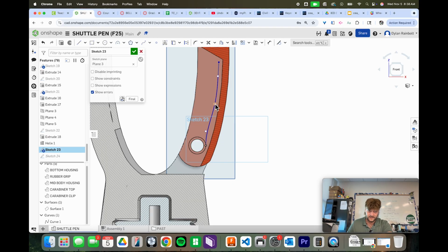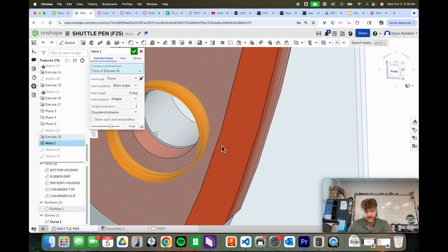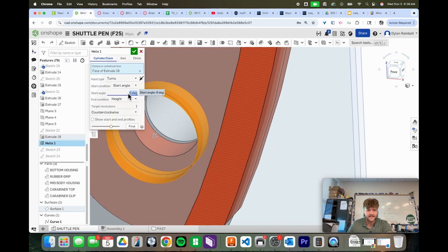It'll flank you. And so now, as you can see, we actually should probably rotate that helix just a little bit. So if I go in here, we want to move it clockwise. So let's try putting a 10 into here. Now that did end up moving it counterclockwise. So I'm going to go -10. And let's maybe put -15 on there. Actually, I'm going to press the green check mark now.